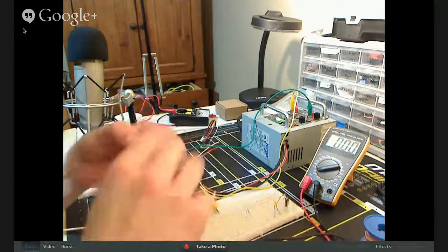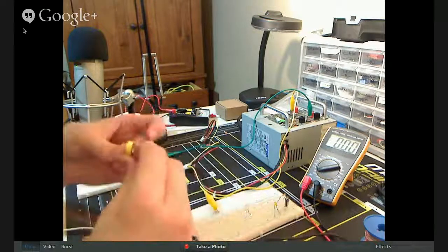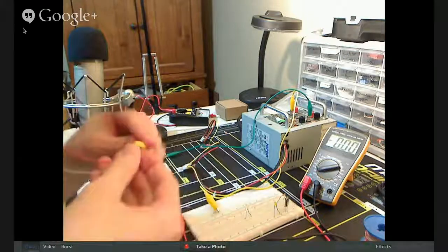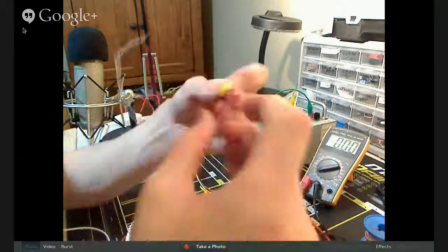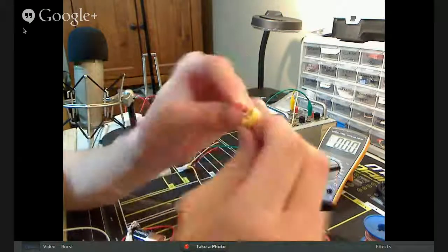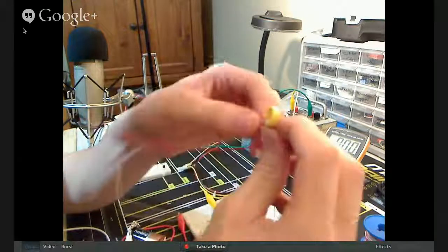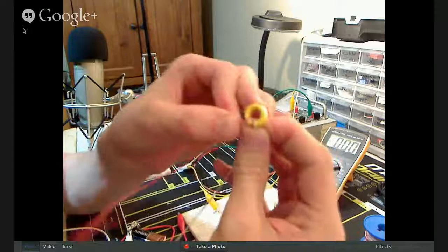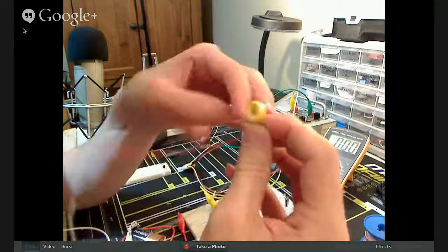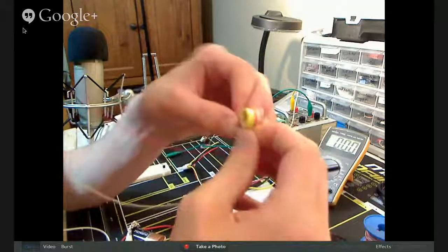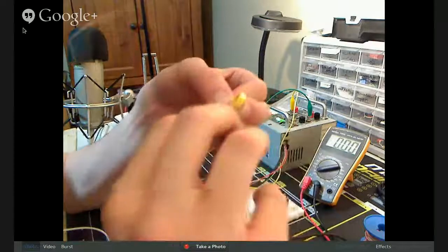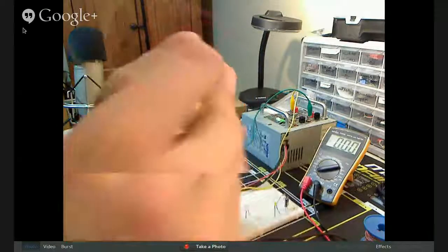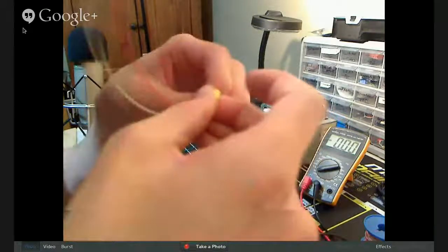Just fit as many as you can. It's important that while you're winding it, you can't do like what I did. You need to make sure that they alternate between the two colors. You can use any wire. If you use the same, I would recommend using two different colored wires. If you use the same color, make sure that they stay on their own sides while you're winding it.